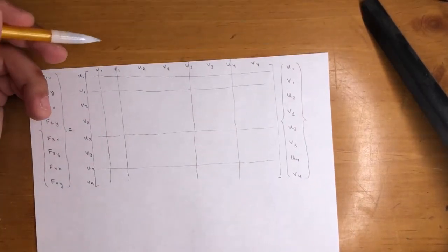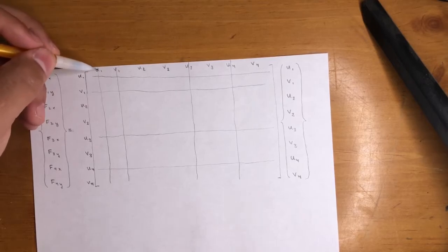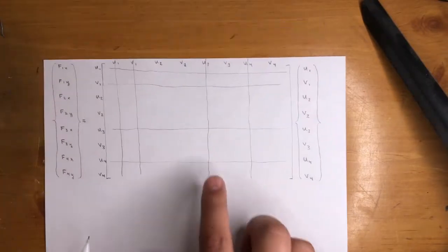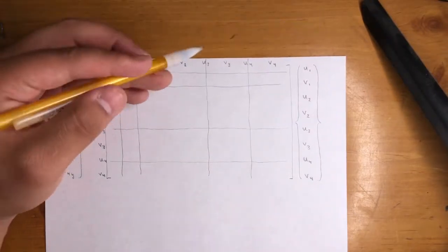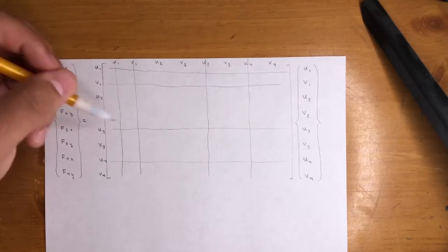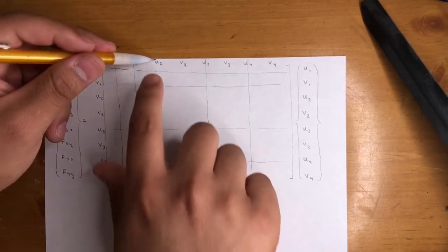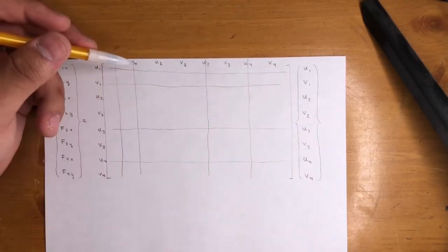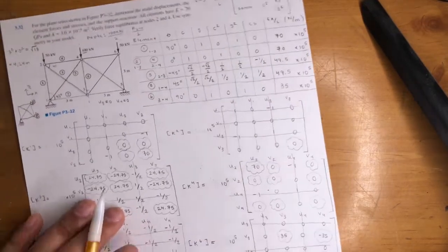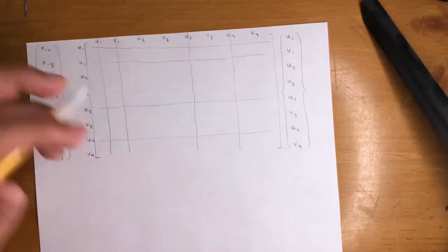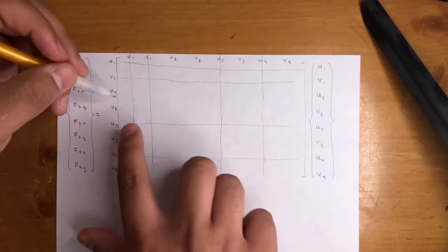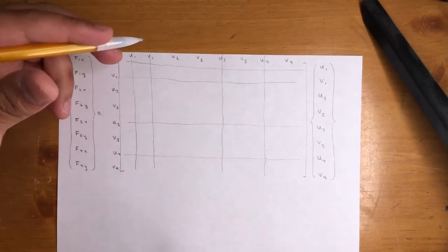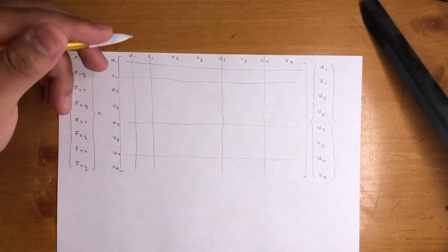I just want to go ahead and show this. The video was playing and I didn't feel like erasing it, but we just applied the boundary conditions just like we did here, remember? When we crossed out, it's the same thing you do for the global equation. So U1, V1, U3, and U4 are crossed out, rows and columns. So that means we care about this 4x4 matrix, U2, V2, V3, V4, and same thing going down. So let's go ahead and do the first row for U2, and then you could do the next 3 on your own. But I'll give you the numbers anyway, so you could verify and make sure you're doing it right. But it's just a long video.